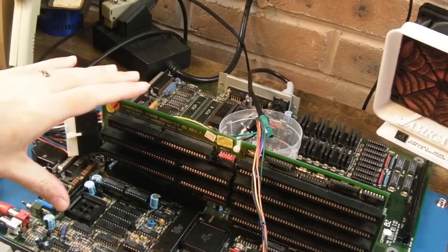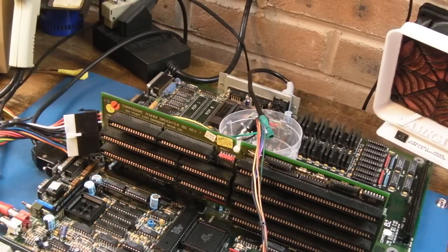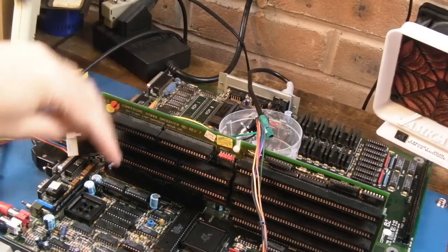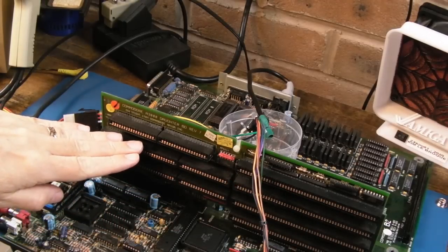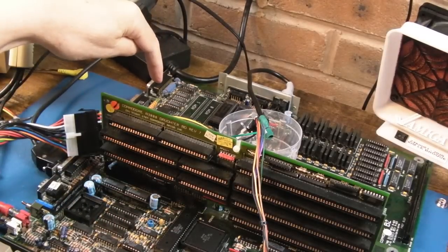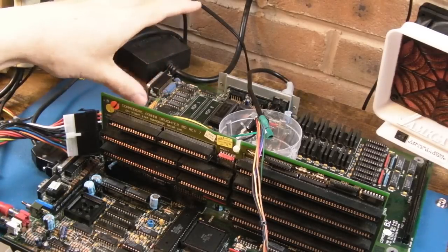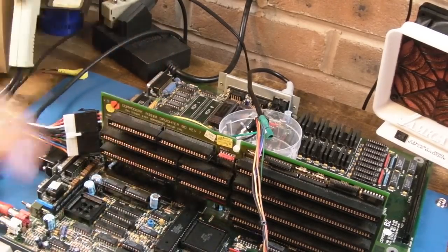I think the next thing I might do is get the ROMs back in. Now bear in mind I couldn't boot from those because I need some sort of floppy to boot from, you know. It's got a weird kickstart, hasn't it? What I'm thinking is I'll get the 2091 with a SCSI card in. No, it's got SCSI. In fact, I could use the onboard SCSI. I could take the one off the A590, the loose A590 I've got. Yeah, let's do that. Let's just try and boot from the onboard SCSI, I think.